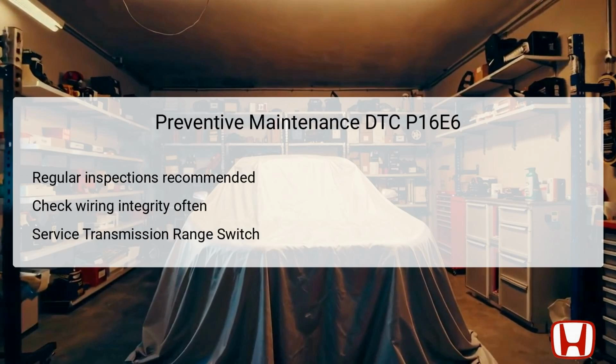To prevent issues associated with DTC P16E6 in the future, regular preventive maintenance is essential. This includes conducting regular inspections of the vehicle, focusing particularly on the transmission range switch and its wiring. Ensuring the integrity of all electrical connections will help mitigate the risk of signal disruptions that could trigger this DTC. Scheduling routine service for the transmission range switch can also extend its lifespan and functionality. By taking these preventive measures, drivers can enhance their vehicle's reliability and safety, reducing the risk of unforeseen issues during operation.